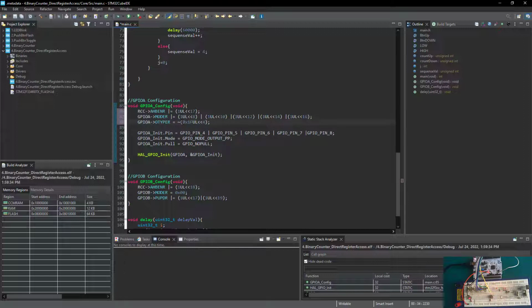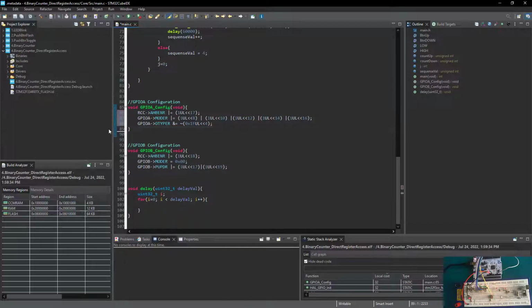So I'm going to invert it, and I'm going to use the AND operator instead of the OR operator, because I need to do the AND operation when I'm inverting so that I can keep those states back at 0. Now, writing this will turn those specific bits into the push-pull type output. Now we can just remove all of this code because we don't need it.